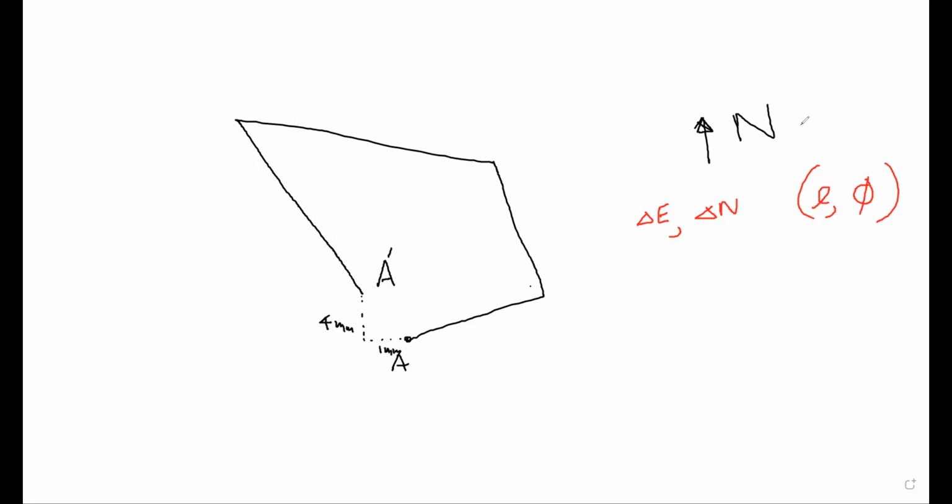But by this time, these bearings, angles are corrected, therefore these bearings are correct. So you can believe that your bearings are okay. Therefore, if you have any error, that is purely due to length measurements. So you can say this error is 100% due to the errors of lengths. So you can claim on lengths.